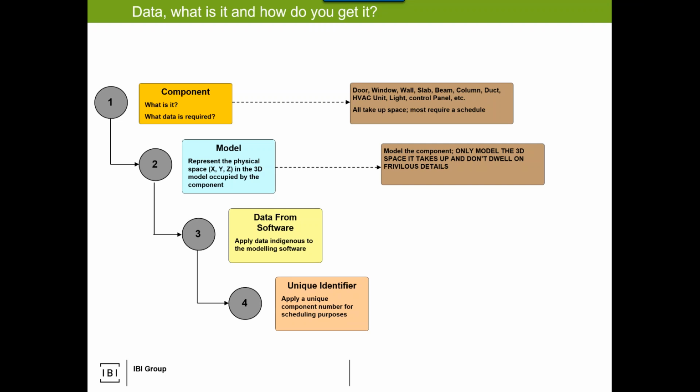So understanding this and not modeling the frivolous details, using the window mullion as an example. A rectangle is great. I don't need to model the actual clamps that hold the glass and the spacers and the desiccant and the sealant. I would never do any of that.